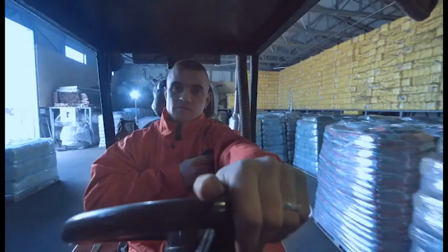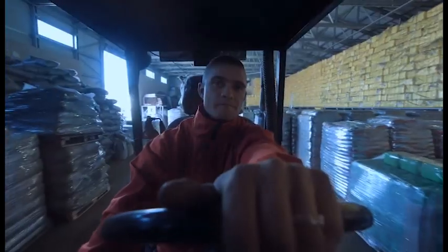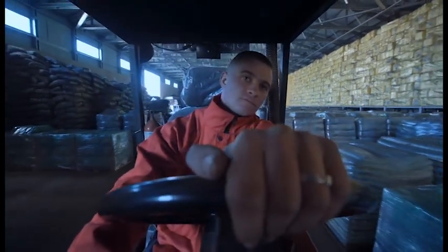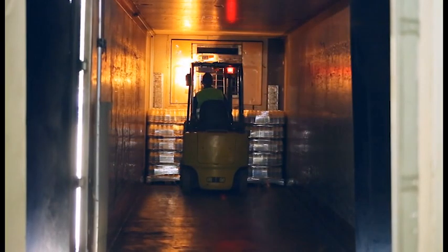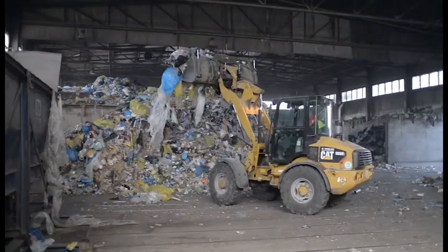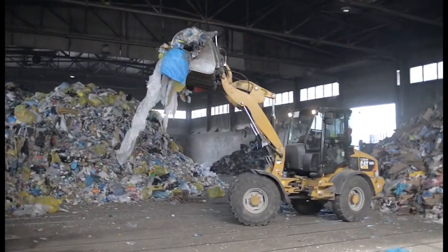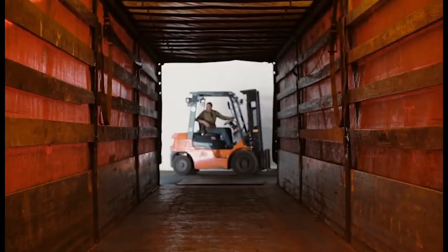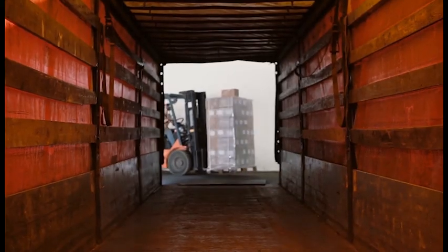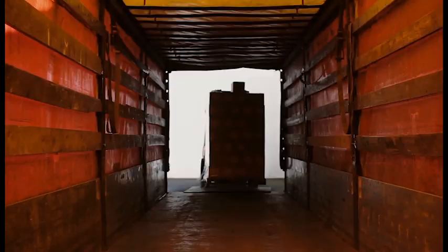Operations. While driving a forklift, operators must be aware of potential hazards, such as mechanical breakdown, fire, overheating, and leakage. Forklift operators must always follow safe operating rules. Never overload a fork truck or extend a load past the center of gravity. Always maintain control of the forklift. Keep a proper lookout and operate the forklift at speeds appropriate for the operation and worksite conditions.